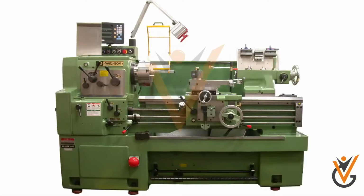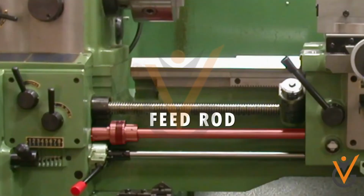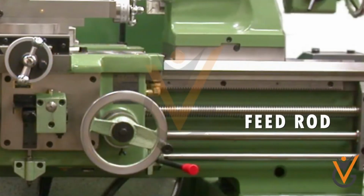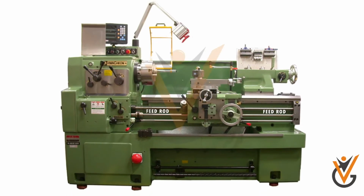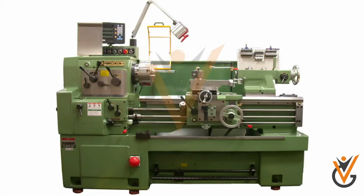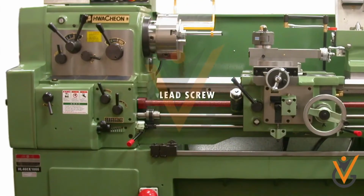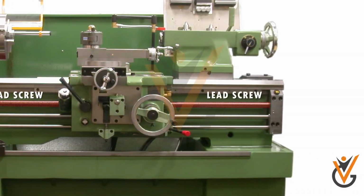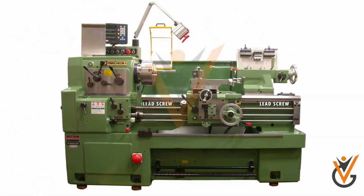Feed rod. Feed rod is a power transmission mechanism used for precise linear movement of the carriage along the longitudinal axis of the lathe. In some lathe machines, instead of feed rod, lead screws are used. Lead screw. The lead screw is used mostly in the case when the threading operation is to be performed on a lathe. As we know, threading operation requires rotational movement of the job, workpiece, and the linear movement of the tool.